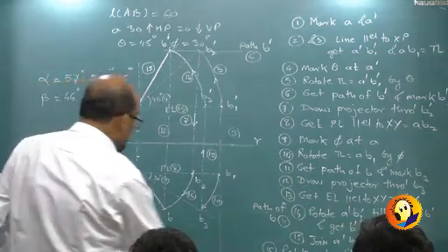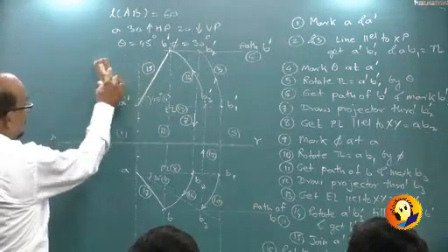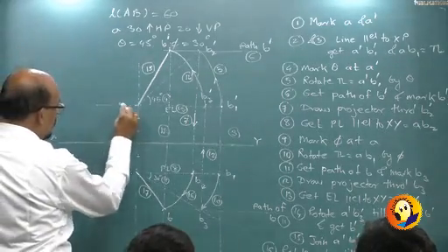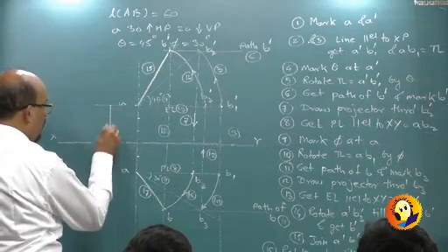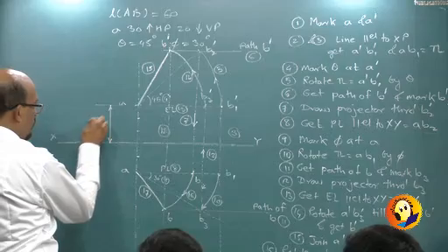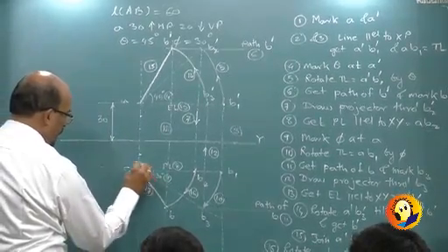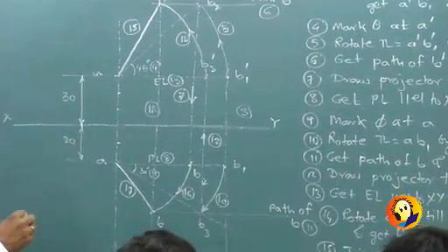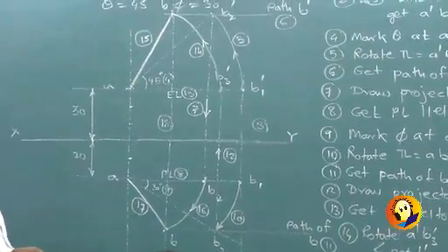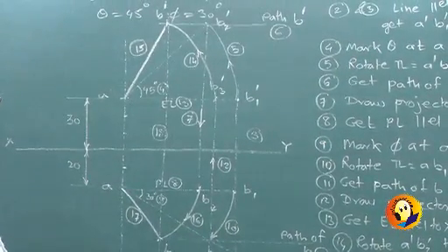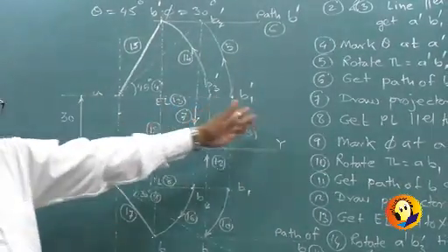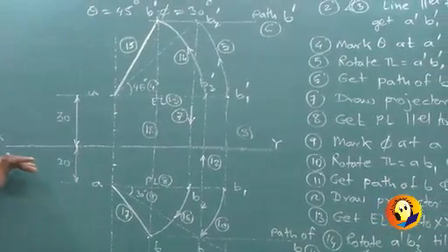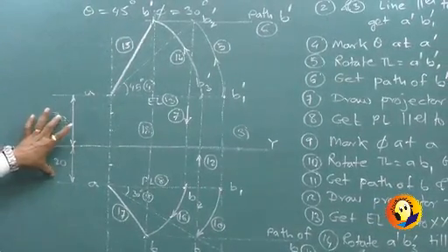And then the dimensions which are necessary. Once we are done with this, for this particular problem, what dimension should be shown, which you are required to show? Of course, you will have to show this distance 30. You will have to show 20. Sir, is it compulsory to show? It is compulsory. Where the point is here, why will you show it here? That's the distance. For this is adjustment purpose, it is okay, but otherwise always leave space for the dimensioning.